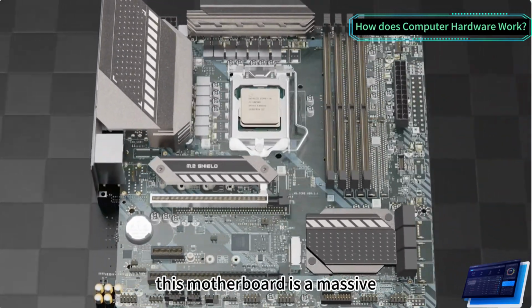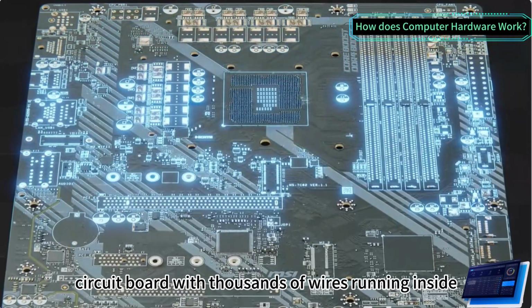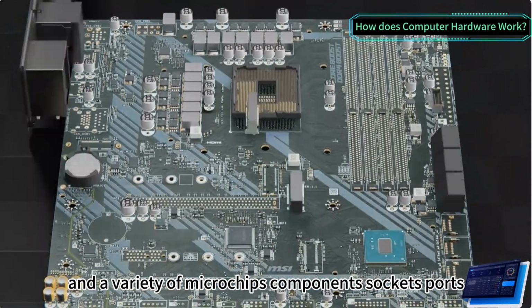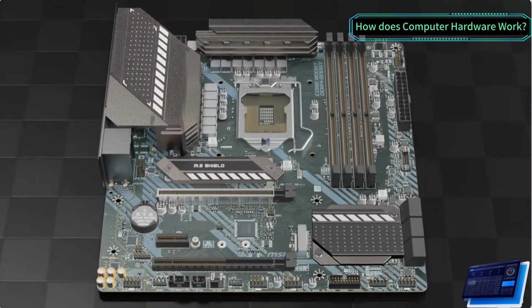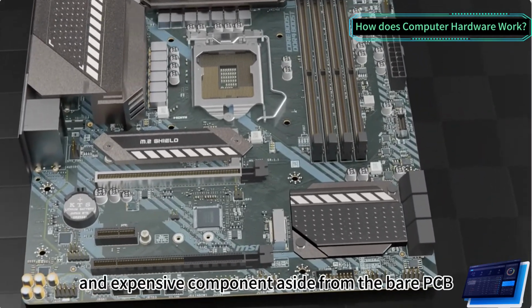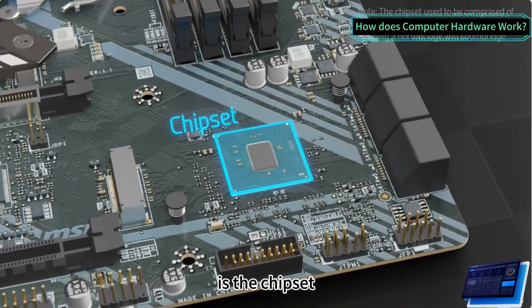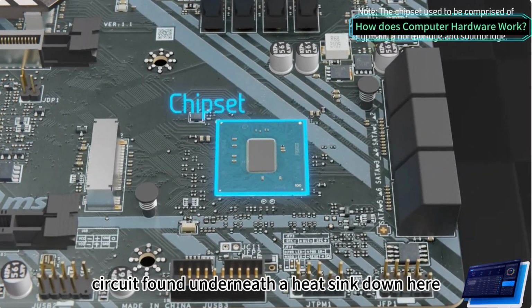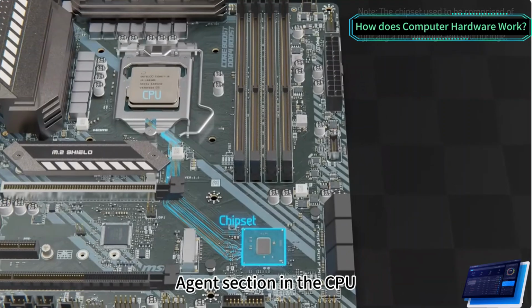This motherboard is a massive printed circuit board with thousands of wires running inside and a variety of microchips, components, sockets, ports, slots, headers, and connectors soldered to it. Perhaps the single most important and expensive component, aside from the bare PCB, is the chipset, which is this integrated circuit found underneath a heatsink down here, and is connected directly to the system agent section in the CPU.